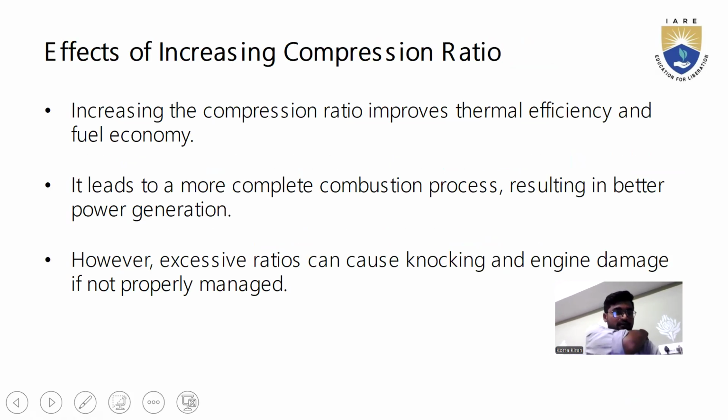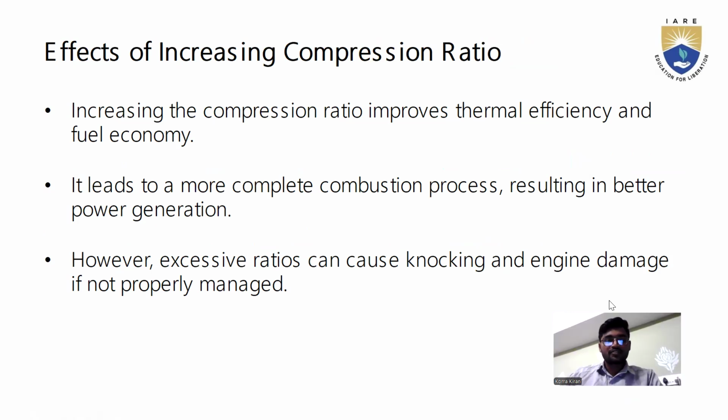Now we can observe the effects of increasing compression ratio. Increasing the compression ratio improves the thermal efficiency and fuel economy. At the same time, it leads to a more complete combustion process, resulting in better power generation. However, an excessive ratio can cause knocking and engine damage if not properly managed.